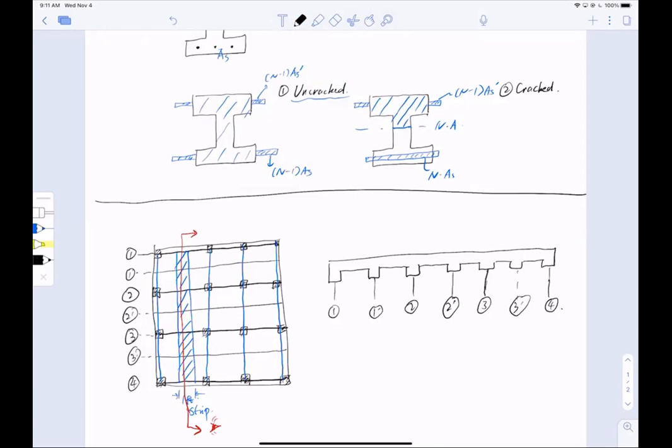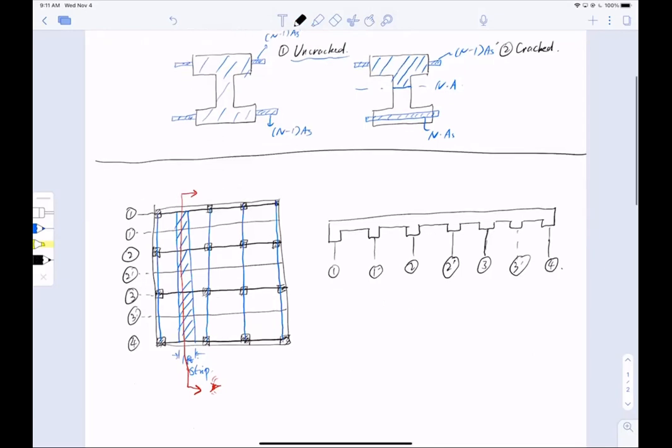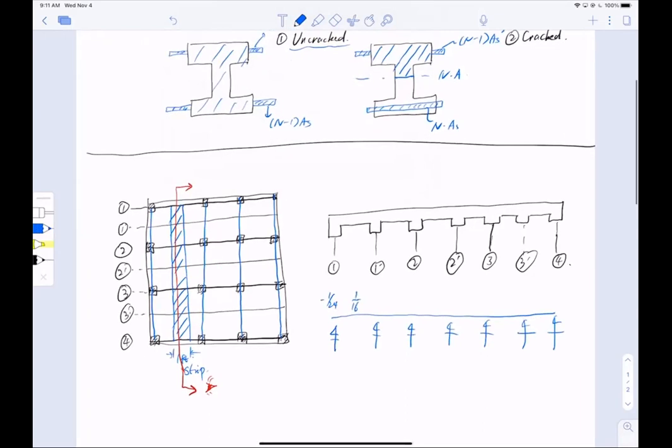So when we talk about moment coefficient, when you do the homework, do moment coefficient, right? Use a blue color. So this is the slab that we're talking about. You have support here, support here, and so on. And those numbers, for example, 1/24, minus something, in the middle is 1/16. I don't remember the number, I'm just drawing out loud here. Minus 10, minus 11, in the middle 1/16 again, and so on and so forth.